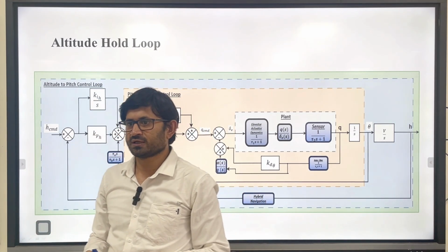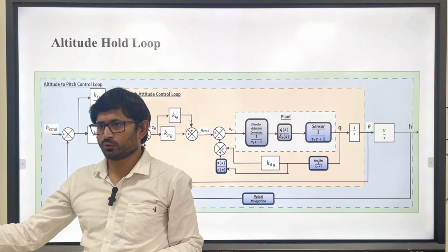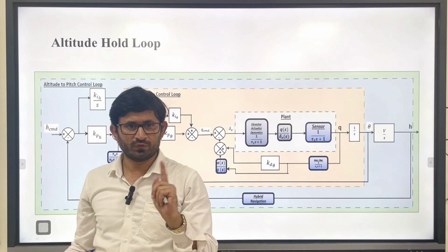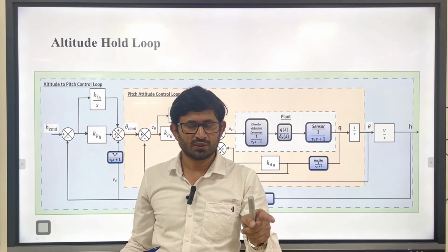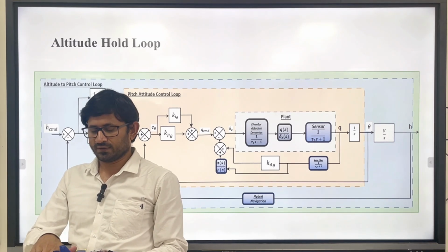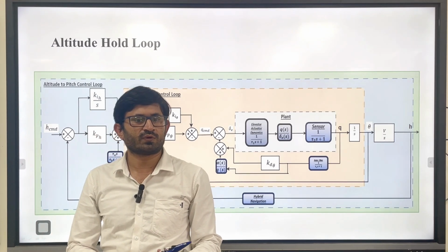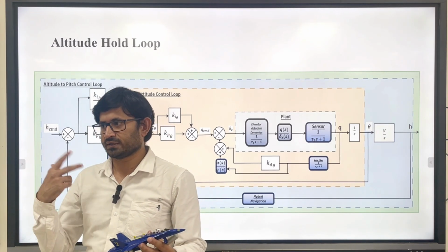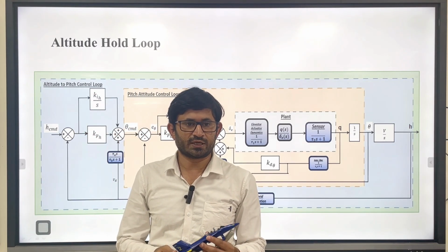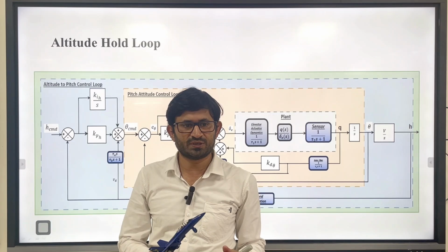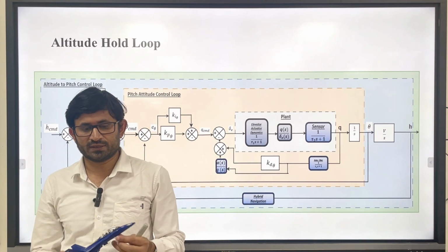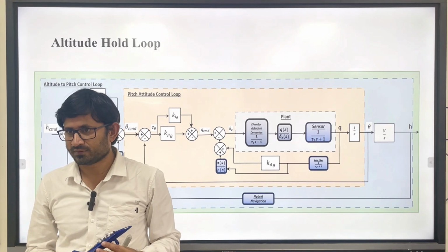For example, in a takeoff, you put the thrust to maximum and wait for V1 speed to be reached. Once it reaches the takeoff speed, you immediately deflect the elevator up in order to rotate the aircraft. Once it is in a climb, you set a particular setting, and by changing the elevator you can move the pitch, and by regulating the pitch you can control the speed.